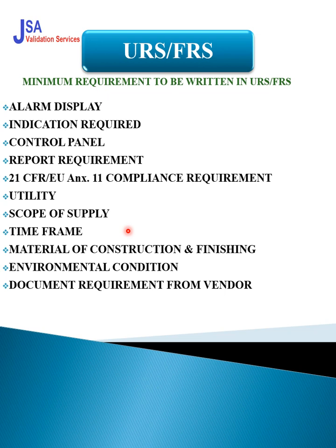So you have to mention clearly which type of construction or material and finishing you require. Also the material for construction and finishing for the compressed air system should be clearly mentioned to meet the GMP requirements. It should not have erosion, there should be no rusting like that. You have to mention everything, which type of material you require, SS, MS, which grade of SS you require.